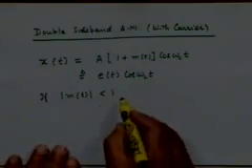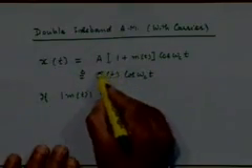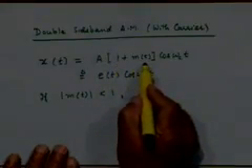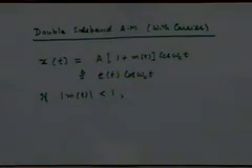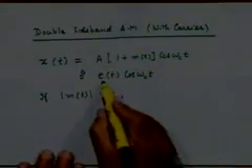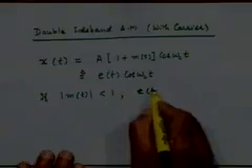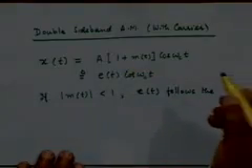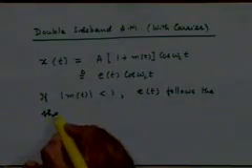In this case, a very interesting property that this waveform will have is that this entity e of t, you see, will be a positive quantity always. 1 plus m(t) will always be a positive quantity. You can think of this as the envelope of the waveform. Envelope always is positive, right? So as you can see, e of t then will have the shape of m(t). So e of t follows the shape of m(t). Of course, there is a constant 1 along with that, but that constant 1 can always be taken care of.